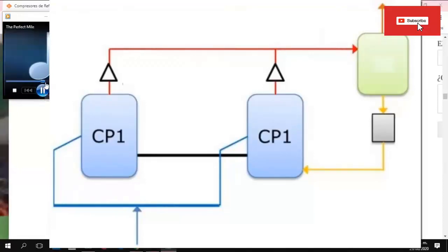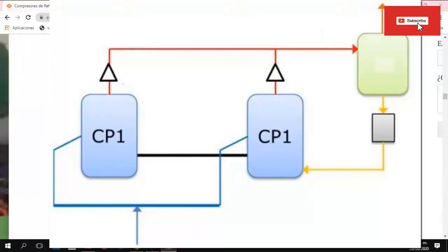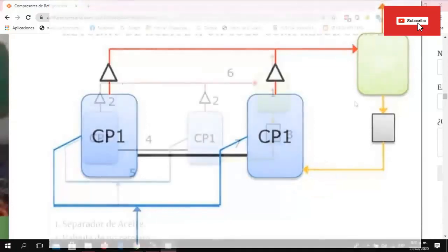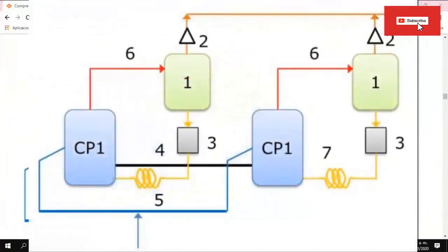3. When only one compressor is running, the oil level of both compressors is within measurement. 4. The oil level of the running compressor is not as stable. 5. When both compressors are running, the oil level is visible and safe in both compressors. 6. The cost is relatively low, however, oil return requires an additional port in the compressor crankcase. This leads to the introduction of another multi-application compressor model.